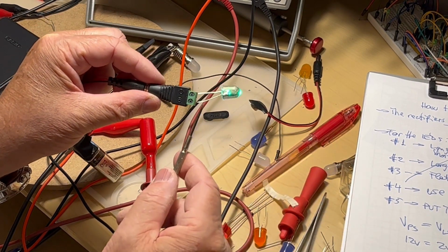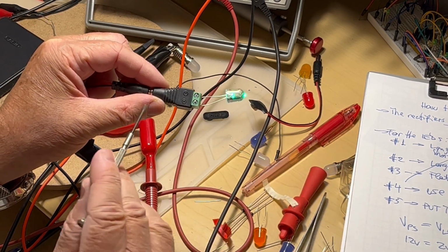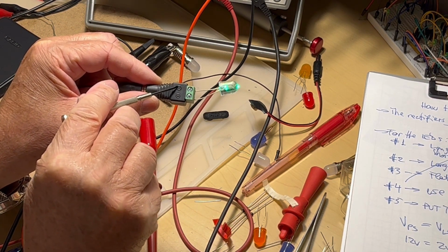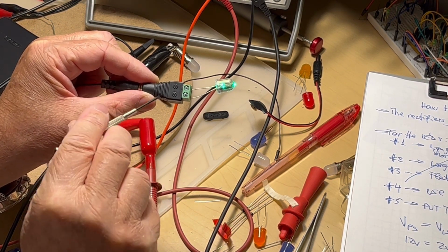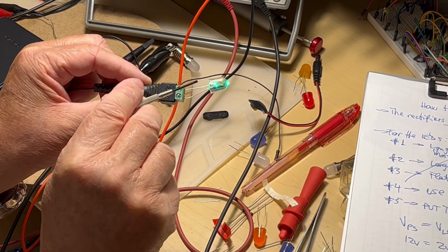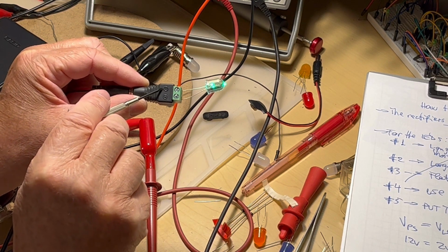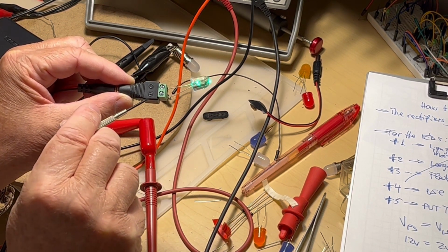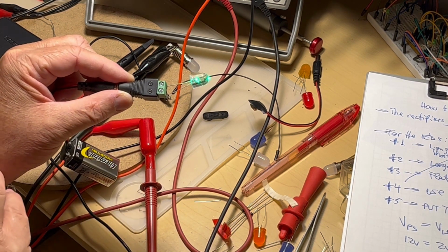And by the way, where is the anode and where is the cathode? While you are energizing the LED, you are going to notice on the connector that here at the top is a negative sign and here is a positive. This is why I chose that particular connector. The negative means the pin of the diode connected to it is the cathode, and the positive means the anode is connected to it. That's how you know the polarity.